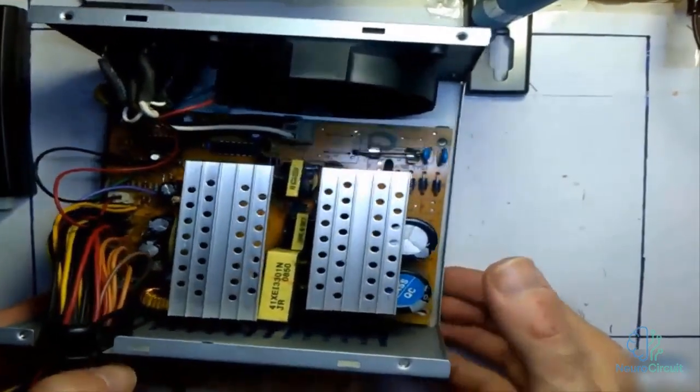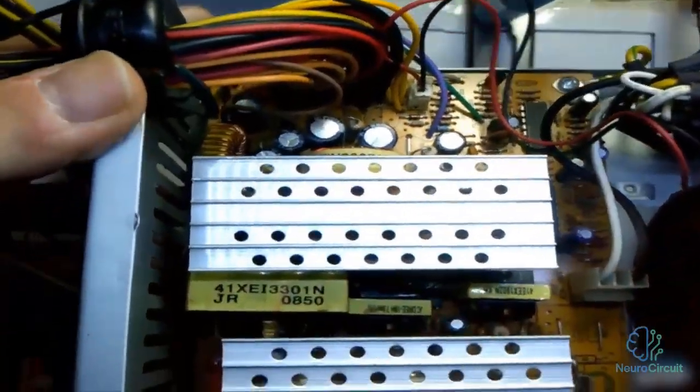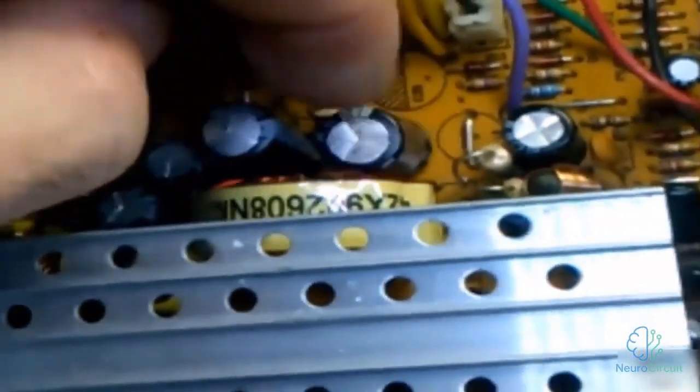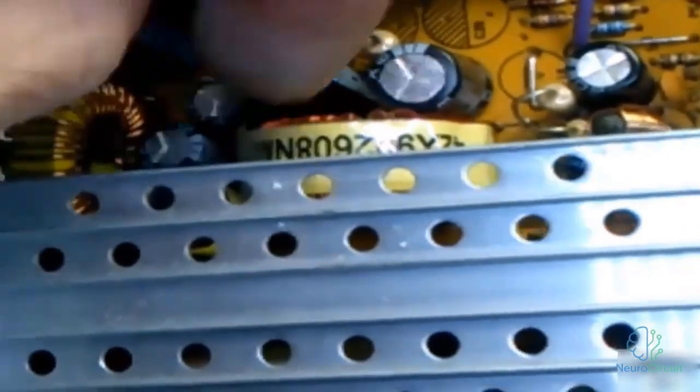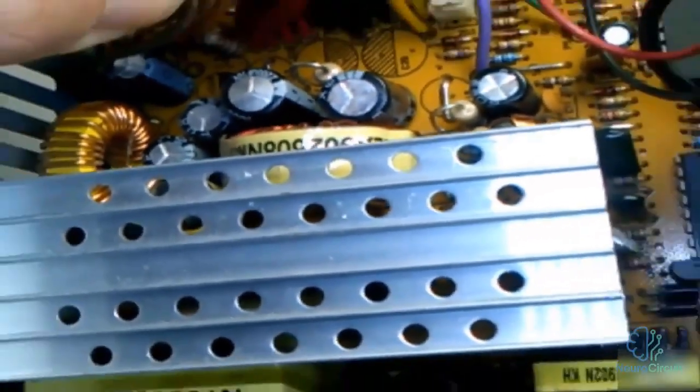Even with this burnt power supply, if we want to take another look at it, you'll see that there are even problems in the capacitors and the output voltage, and some components are faulty. Take a look. Here, for example, one of the capacitors and the second one, two of the capacitors on the output voltage side are swollen, and their damage is completely obvious.